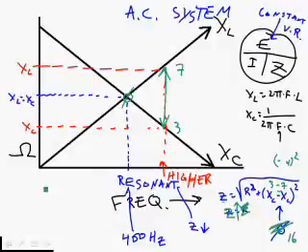So if the frequency goes too high, then the value of Z, or impedance, is going to go up. Well, if we have a constant voltage and impedance goes up, that is, the opposition of current flow gets worse, then current flow, more opposition, less current. So if impedance goes up, then amps is going to go down.